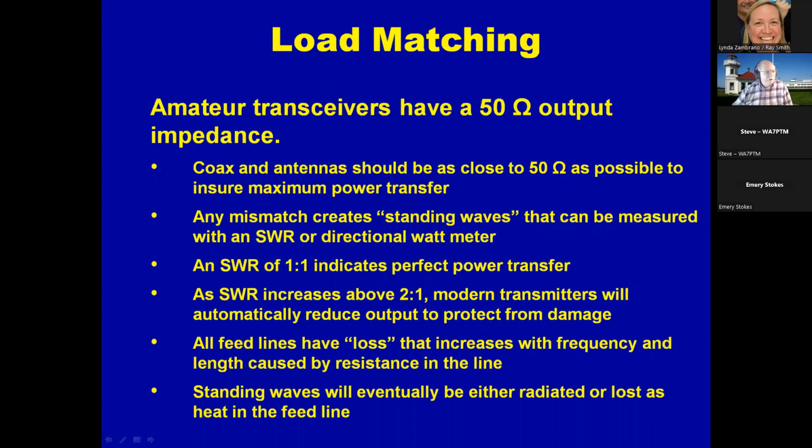And it creates what are called standing waves, where the energy, if you're in a bathtub and you create some waves, when they bounce off the side of the bathtub, they're going to hit the incoming wave, and they're either going to offset it or they're going to magnify it, depending on how they hit each other, right? So that's what happens with a standing wave in a feed line.